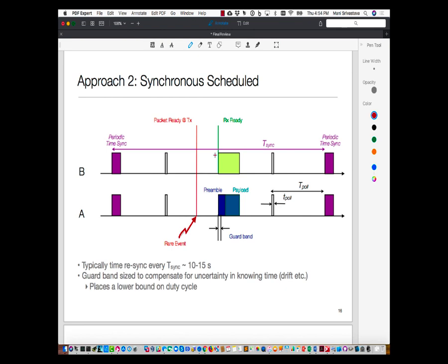Obviously, there's a latency challenge here, because I have to wait until the next wake-up episode. So whatever my duty cycle period is, divided by 2, is the expected latency. And if you are sending this through a network, then there is a potential latency issue at each of these hops. But there are sometimes optimizations where the packet can just race through. The whole network has woken up, and we make use of that opportunity to bubble the packet through instead of repeating this process every time.